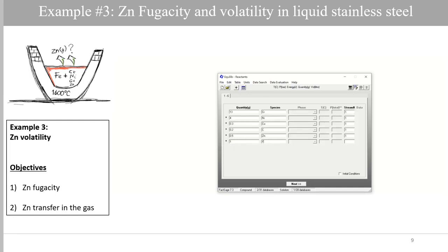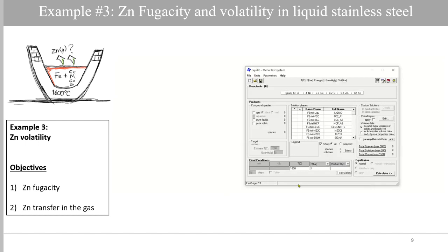So I'm going to put iron, and there's an option in FactSage, so you can click on question mark 100, and this will evaluate the rest of the 100-gram basis to obtain your overall mass balance. So we're ready in terms of mass balance. We don't need to activate the initial condition because mostly what we want to check at this point is, like I've mentioned, the volatility of zinc. And we can click on next.